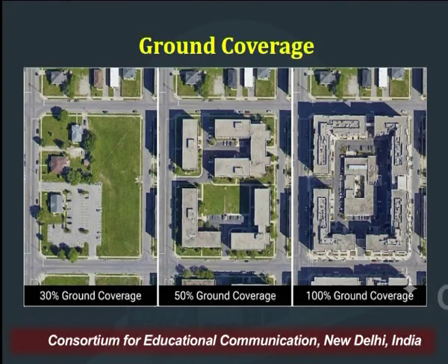So in our building bylaws for residential purpose also, you will be getting these numbers. So this means that how much of the overall site area that you have got the building can cover will be given by the ground coverage value from the building bylaws.